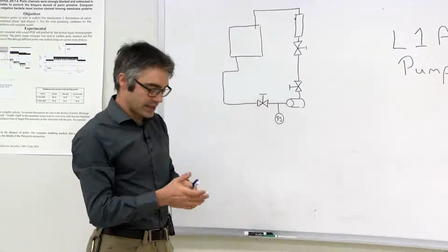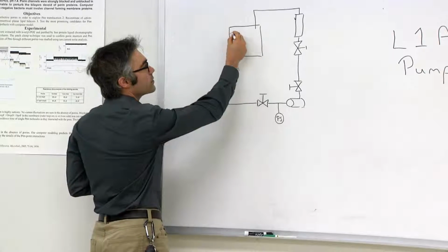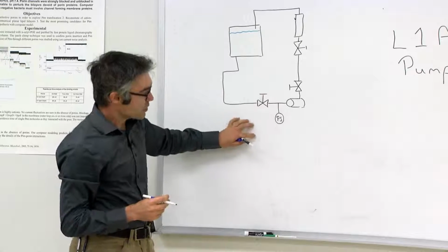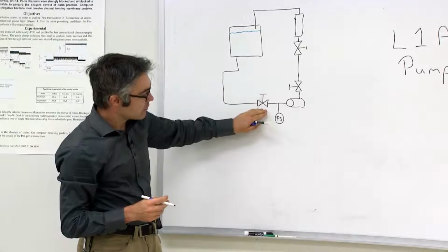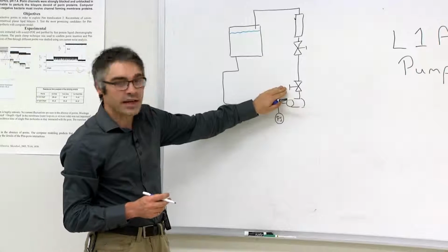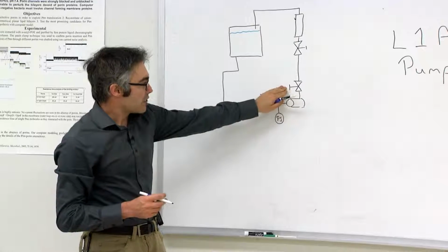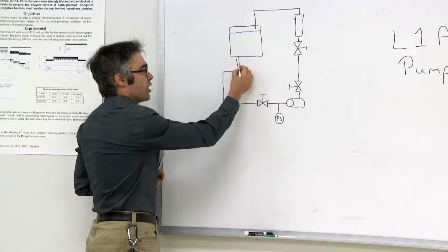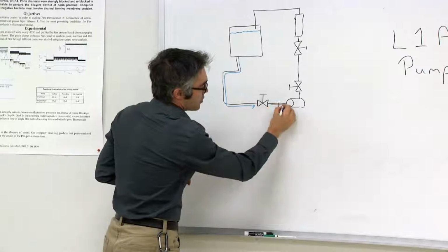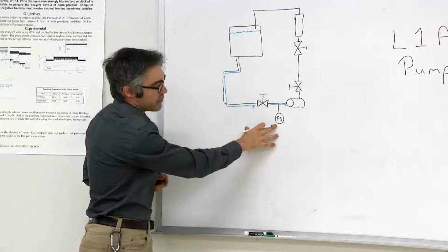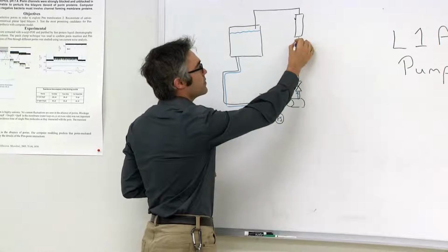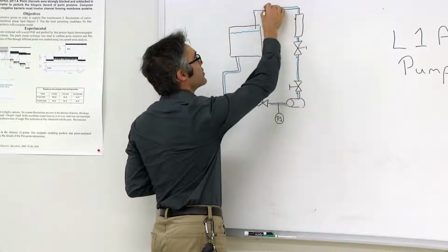Conceptually, this laboratory is fairly simple. We have a reservoir of water and an apparatus containing 4 pumps. You must make sure that the valve before the pump and after the pump that you'll be using are turned on. You'll be assessing 1 pump at a time. The water will be drawn first through gravity, then through the pump. Through the pump, you'll be reading the pressure at the inlet of the pump. The water will then move up through a rotameter and back into a reservoir.